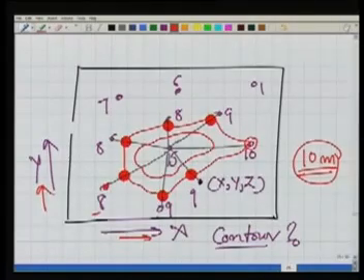So this will be a contour of 12 meter. So what we are doing, using our randomly collected data in the field, there were some randomly distributed points. We determined their x, y, z, and now on my map sheet, I am drawing the contours by interpolation. This is what we are doing.